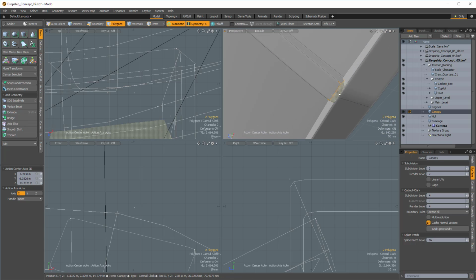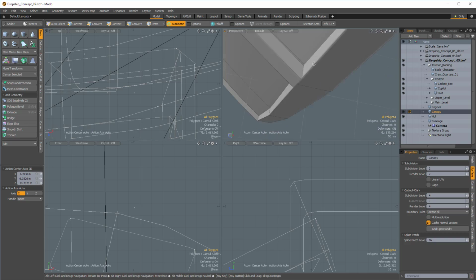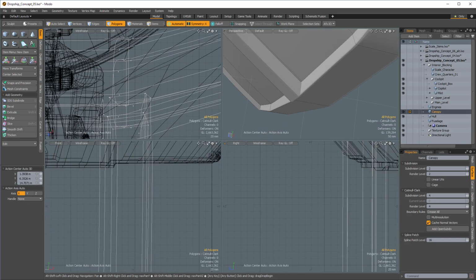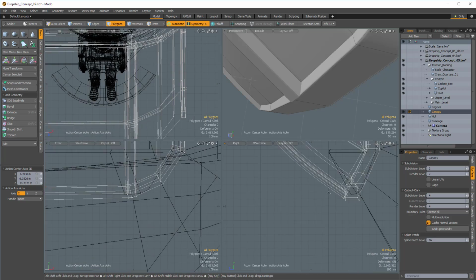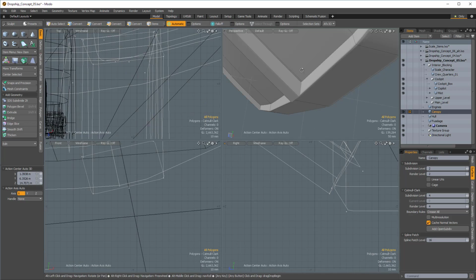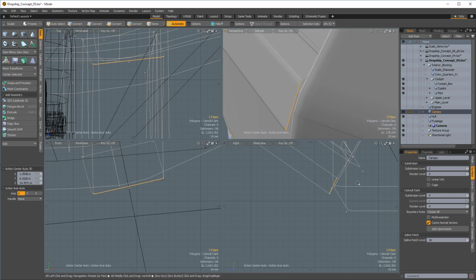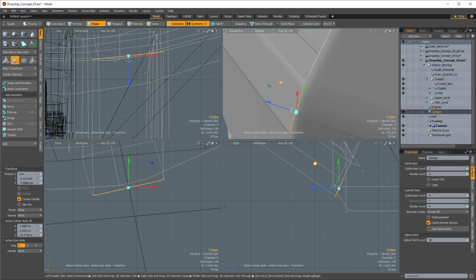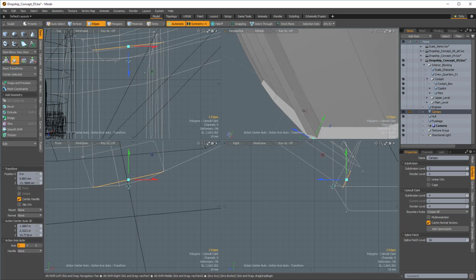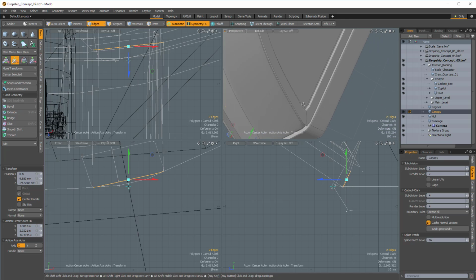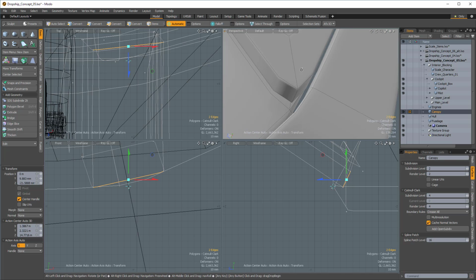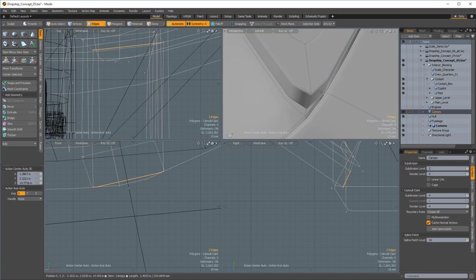And we'll do the same thing on the bottom here. So I'm going to take this polygon and cut it out. And sometimes just removing that polygon will fix the issue. But we're going to go down here and just double check. And it looks like we have a little bit hanging out. Yep, we do. So we'll just grab that move tool and just pull that back down into the housing. Oops, and then make sure we're up high enough to get that little bit of overlap. Now this one I don't really have to worry about because it is kind of sitting up against here anyway.